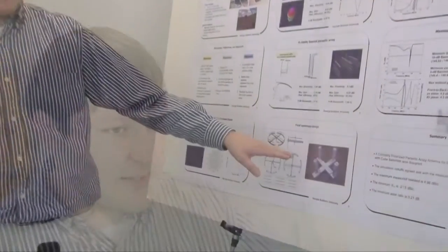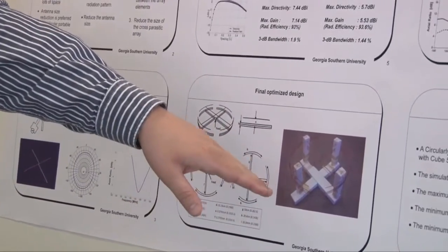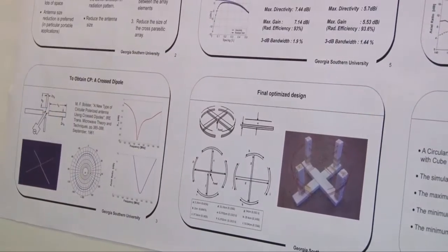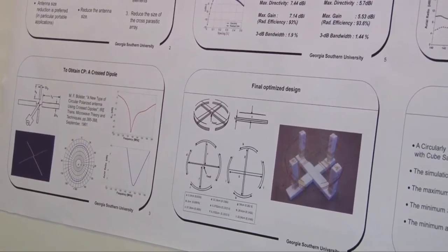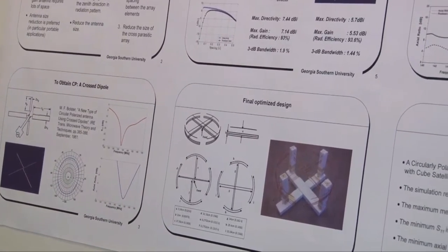The final design of the antenna used the triple folding method along with a curved top loading to get the geometry into the smallest size possible. The final size came to be 1/4 meter wide and 0.04 meters thick. So, a significant size reduction from the standard antenna that would be used for CubeSat communication.